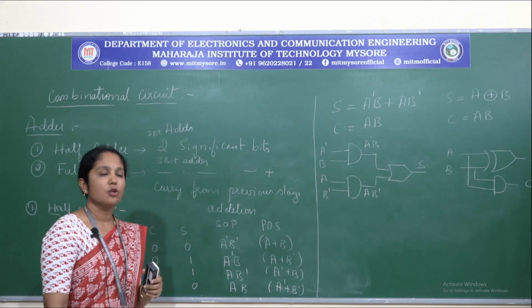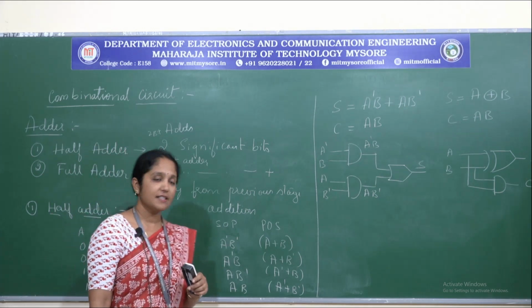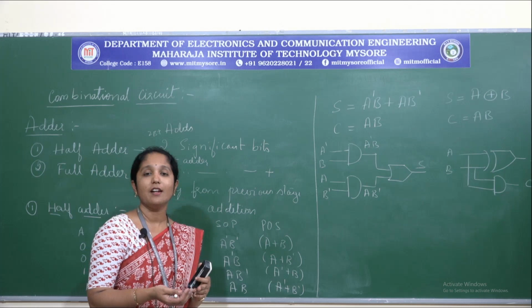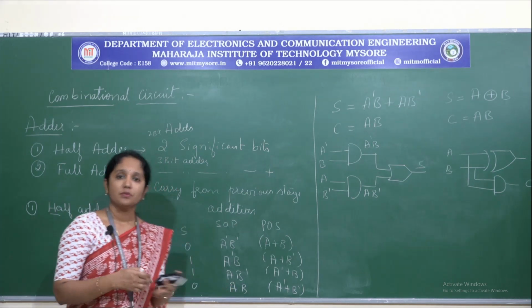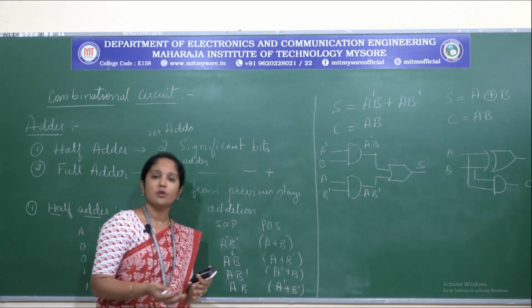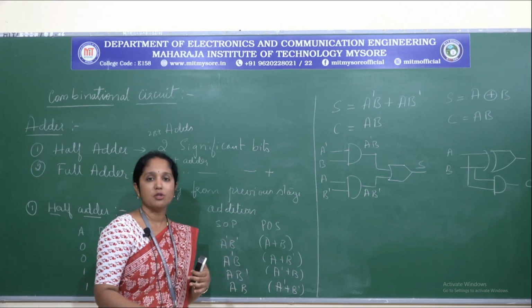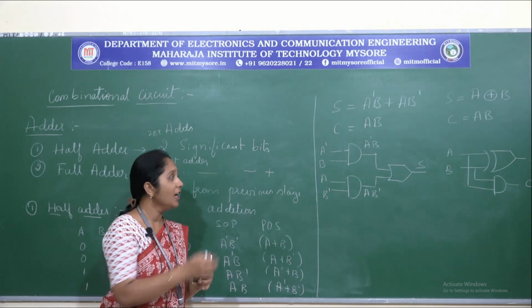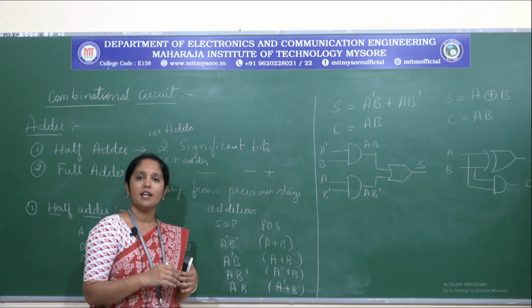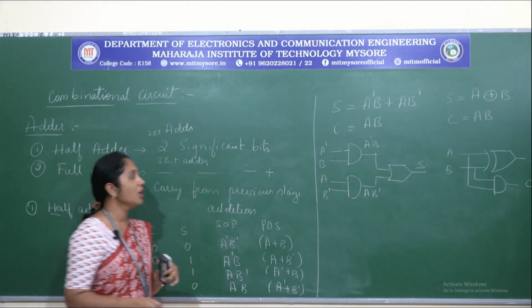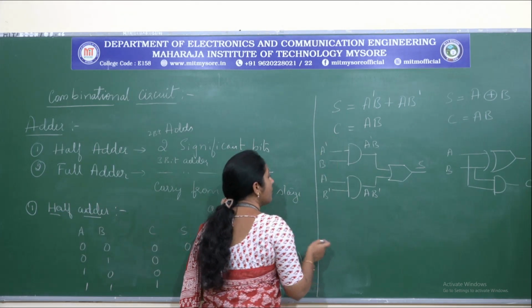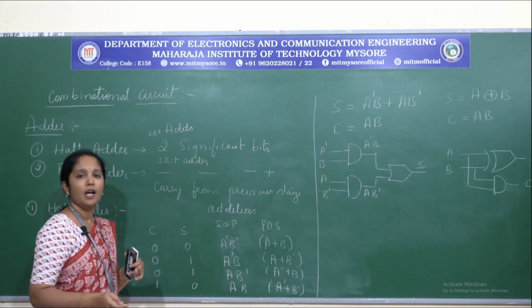Other than this, we can have another 3 circuits for half adder. In order to give options to a designer, we can go for any of the circuits, any of the equations we have here. Let us see all the equations. Now we have 2 equations, and this is for SOP. Next, let us consider the POS form.